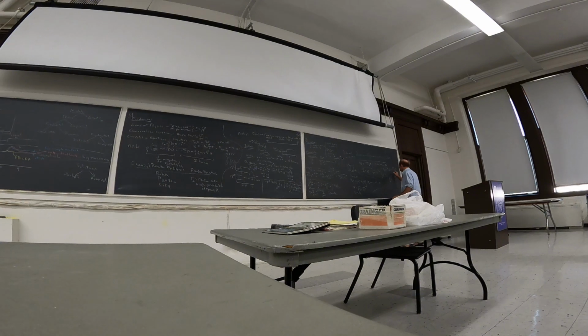I can integrate from 0 to t. And this is from e to the 0 times CA of 0, to e to the t over tau times CA. And what do I get? Here I get CA e to the t over tau minus CA of 0 is equal to CA in over tau times this integral.